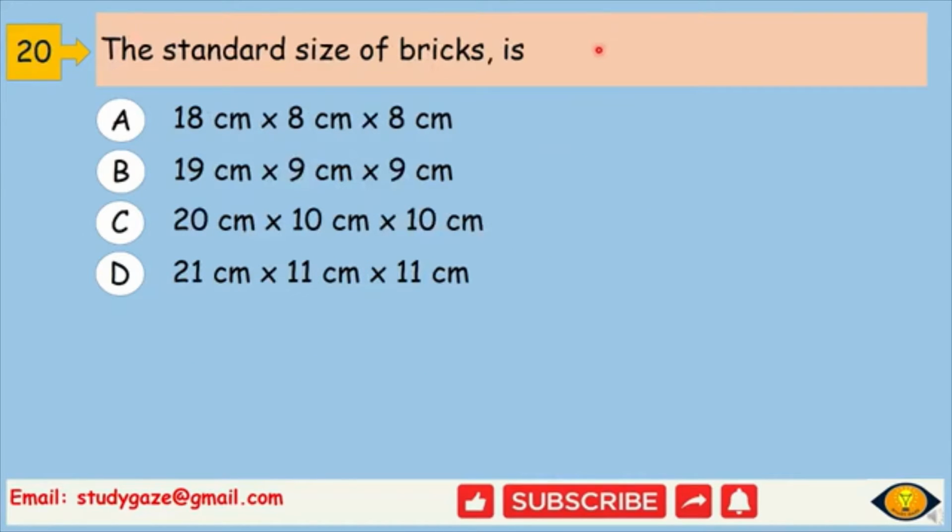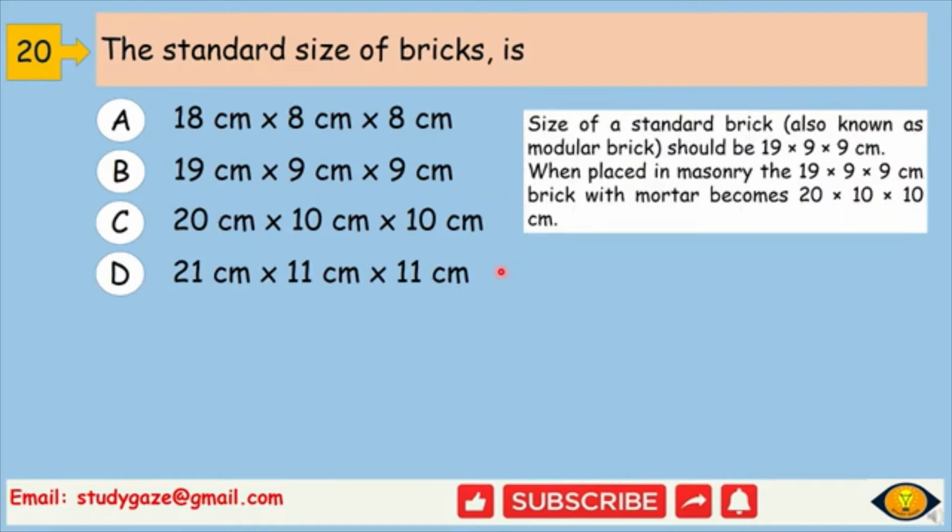20. The standard size of bricks is 18 centimeter by 8 centimeter by 8 centimeter, 19 centimeter by 9 centimeter by 9 centimeter, 20 centimeter by 10 centimeter by 10 centimeter, 21 centimeter by 11 centimeter by 11 centimeter. The answer will be B, that is 19 centimeter by 9 centimeter by 9 centimeter. The size is standard, whereas when placed in masonry, the 19 by 9 by 9 centimeter brick with mortar becomes 20 by 10 by 10 centimeter.